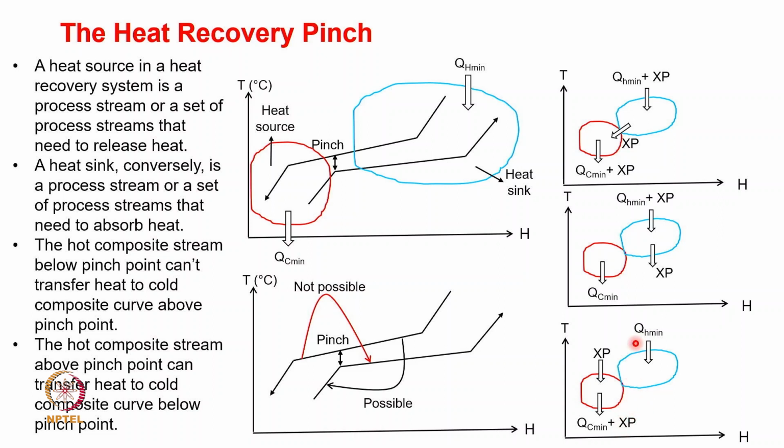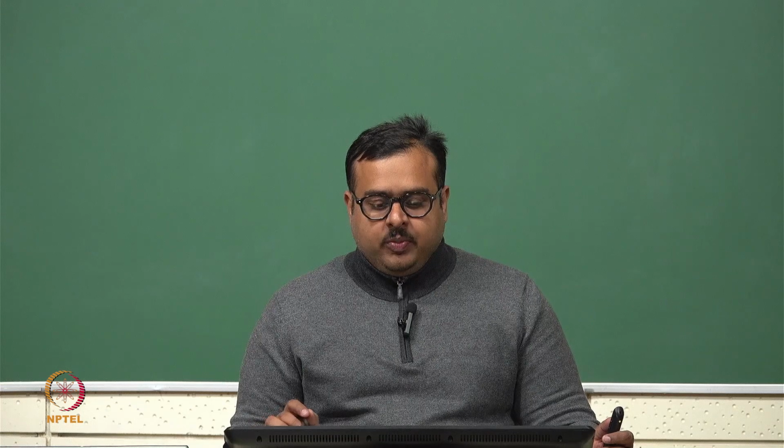So this kind of additional heat addition is typically not recommended. Why? Because especially when you add heat in the cold stream, it would typically increase the heat of the cold stream and eventually heat transfer becomes more constrained. Okay. So a proper arrangement would require not just addition of heat, not the removal of heat arbitrarily, but following the correct principles of heat recovery.